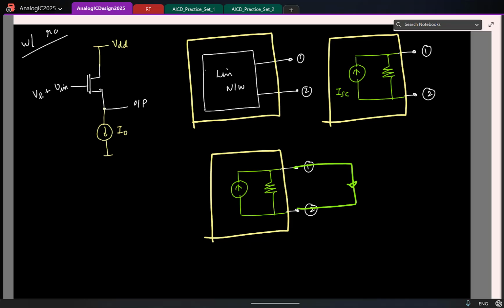And this Thevenin or Norton resistance is the effective resistance seen across this port, which I'll call the output resistance Rout, because that is essentially the resistance seen across the output port. So instead of calling it a Thevenin or Norton resistance, I'll say it is the output resistance, the effective resistance seen across that port. Fine.